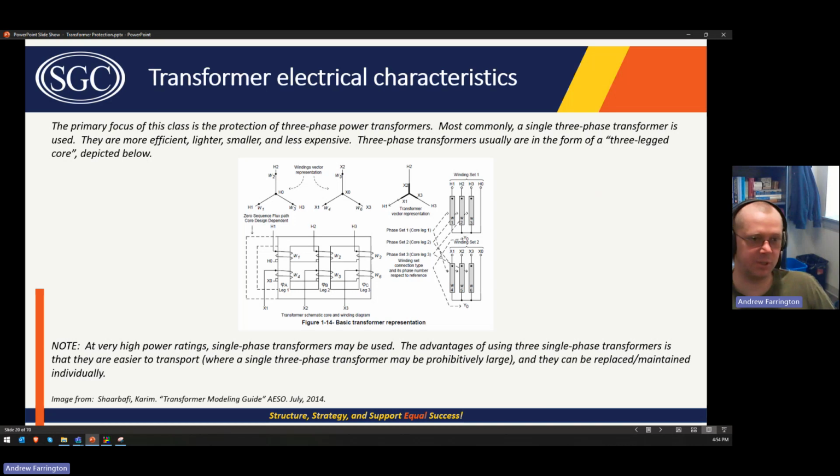There are bridges, other clearance concerns, traffic, the angles around turns, what have you, right? Tilt in the road, all kinds of different considerations for physically transporting it. So you can imagine if each of these massive single phase transformers were going to be combined into one 3-phase transformer, just the sheer size of it would make it impractical to actually use.